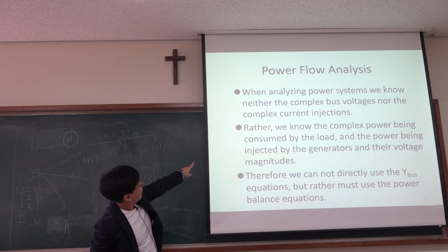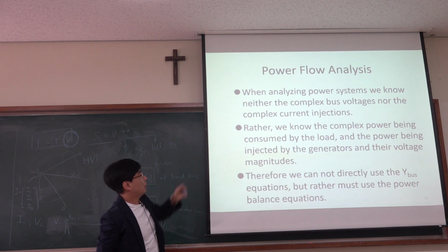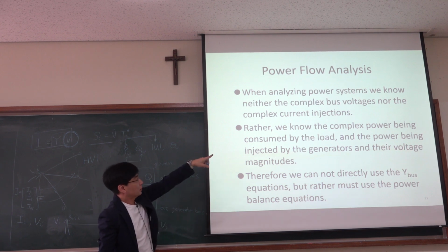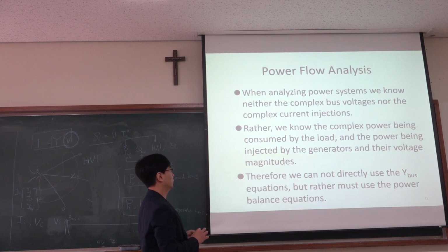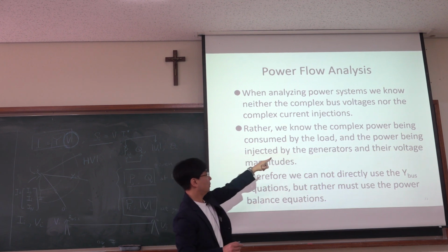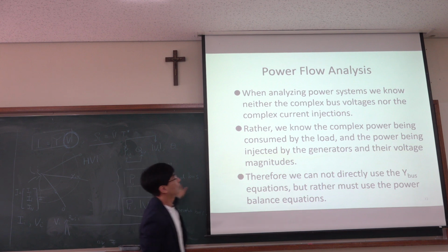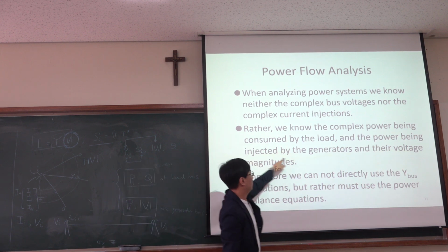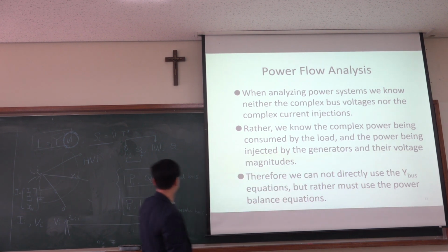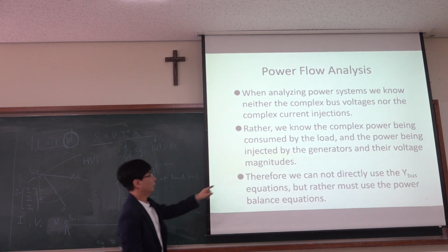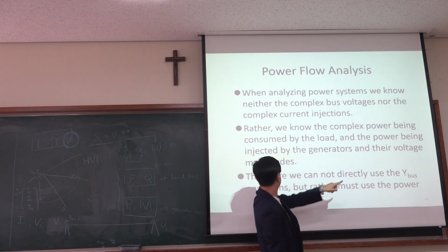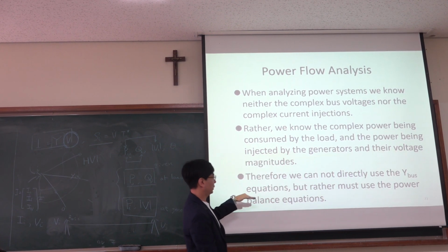Where are we? We are here. When analyzing power systems, we know neither the complex bus voltage nor the complex current injection. Rather, we know the complex power being consumed by the load, this one, and the power being injected by the generators and their voltage magnitudes, this one. Therefore, we cannot directly use Y bus equations.